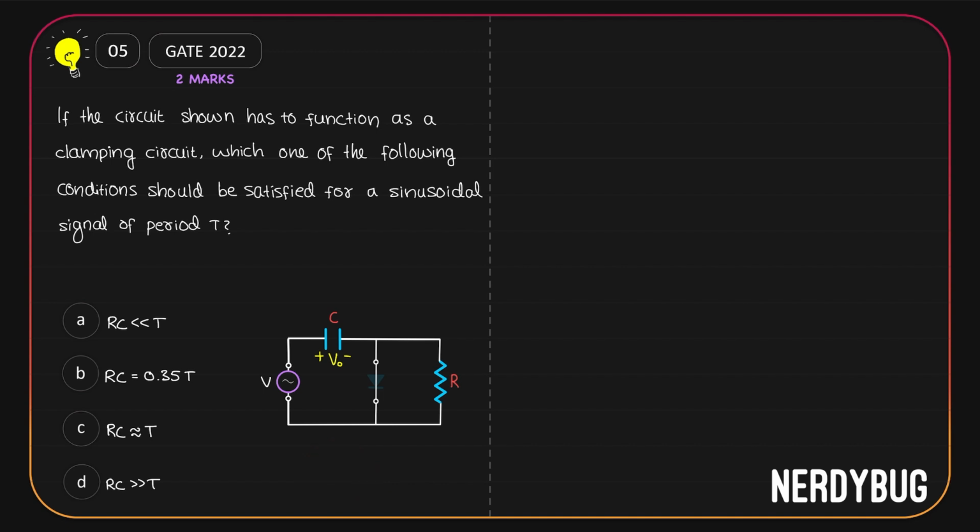See, the capacitor has positive potential on this plate and negative potential on this plate. So if the capacitor has to discharge, electrons from this plate have to go in this direction to the other plate. That means current has to flow in this direction. Can the current flow through the diode like this? No, because in that case, through the diode, current will be flowing from the N side to the P side, which is not possible. Let's consider the negative half cycle.